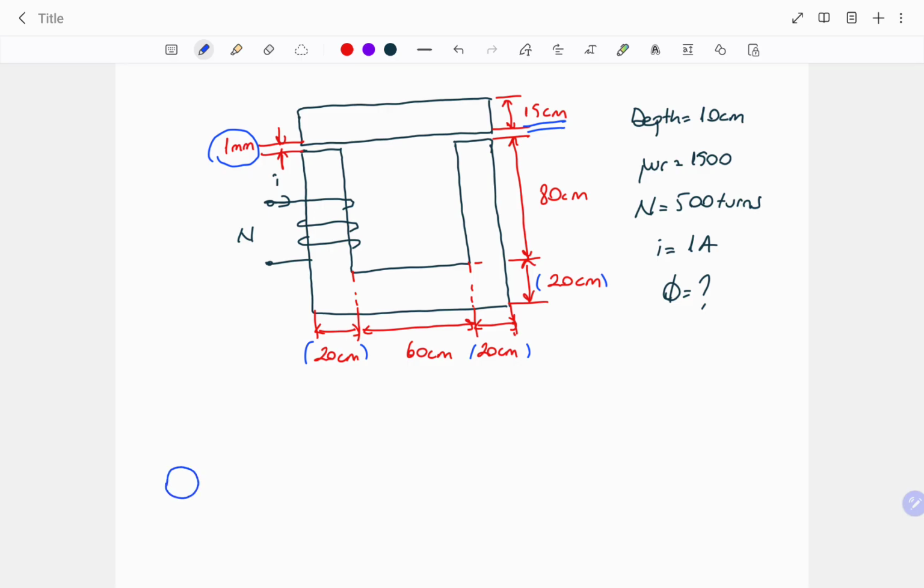We have a single source which is located on the left side. Through the magnetic circuit, first of all, we can start with the air gaps. All the reluctances will be connected in series, so their places will not change anything. We have two air gaps, so we must write two air gap reluctances for the left and the right side of the circuit.